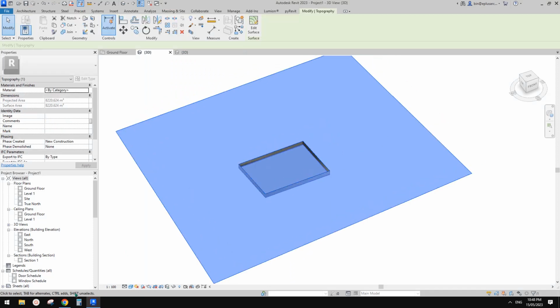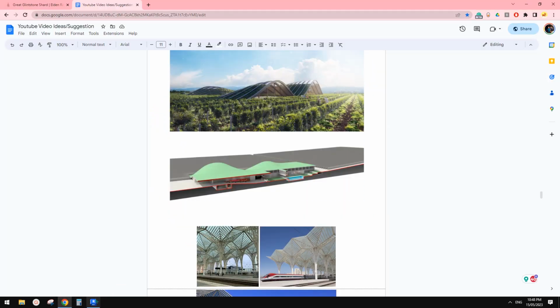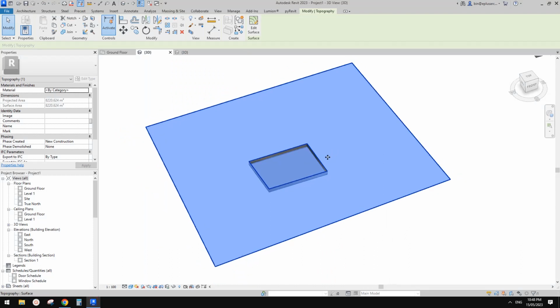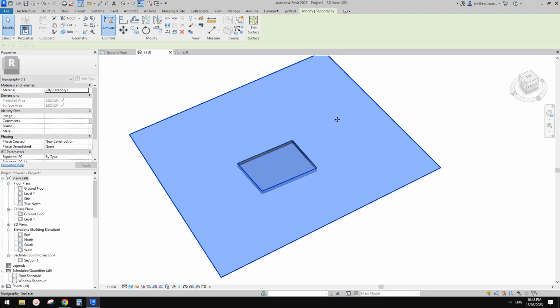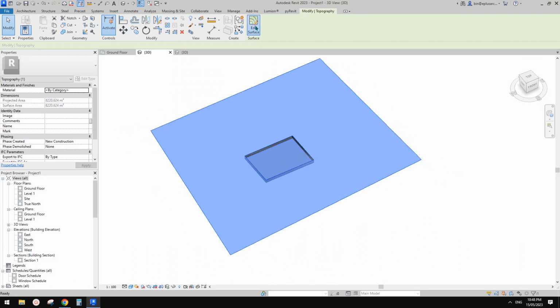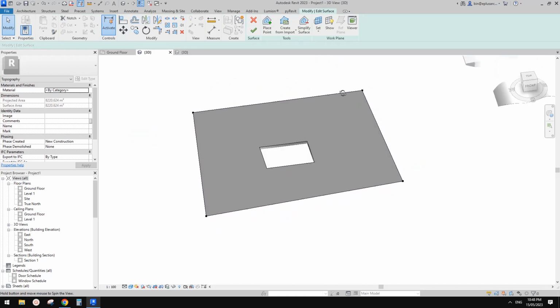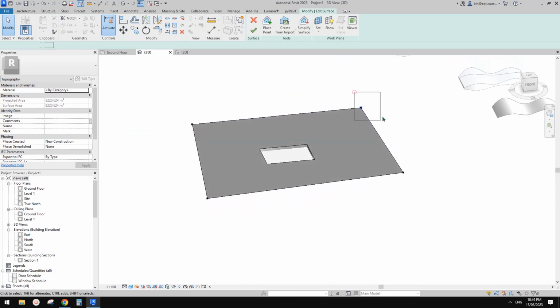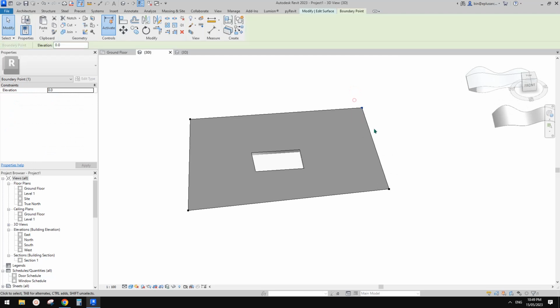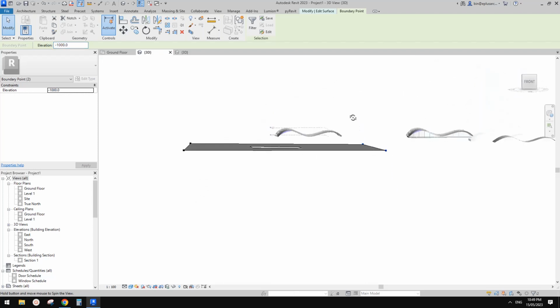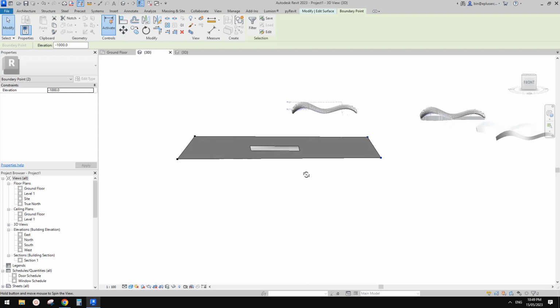So basically, it's not that easy to adjust top surface. So usually, for example, if you want to lower that, you can adjust those points. So for example, if I change to -1 meter, the whole side will become sloped. So you can see this is 0, this is, maybe make it more, -3 meter.